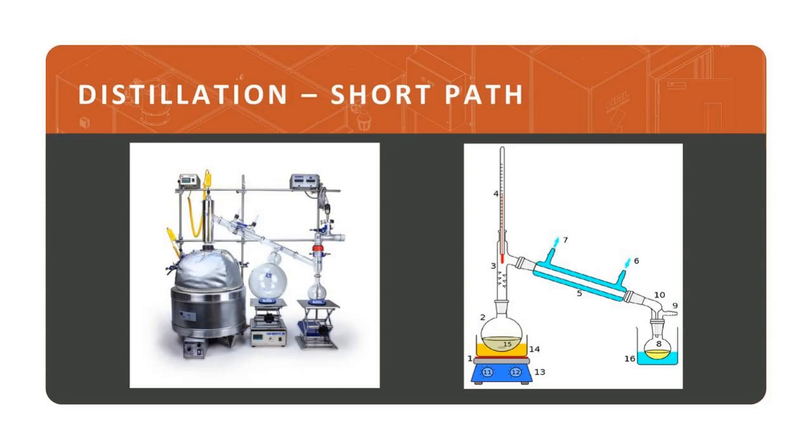And so this entire system is going to be under pressure, typically as low as you can go. At sea level, we're looking at negative 29 inches of mercury. We're in Colorado, so sometimes I remember only being able to pull like 26 inches, but you want to pull as deep a vacuum as possible, which allows you to boil off these compounds at lower temperatures, preserves the integrity of those compounds, and means that you won't be dealing with any nasty terpenes, for example, because terpenes will off-gas at a lower temperature than your desired THC.